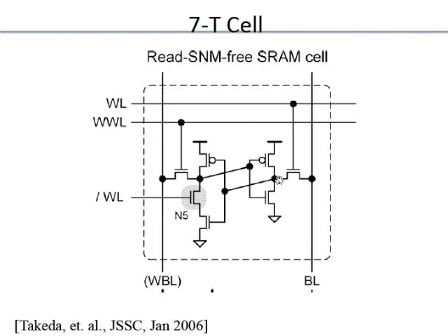Now if the data is 0 is when we said we could have a problem of flipping the cell, because when the data is 0 here, I have a current flowing through here which can cause this to go up and bump, but that is prevented by this. When this is 1, there is no issue because bit line is also pre-charged to 1, this is also 1, there is no current. You wait for some time, if the bit line is not discharged, you just call it a 1 and go ahead, right? So the way you sense a 1 is, you give it some fixed amount of time and then you sample the bit line. If it is not discharged below a certain value, you say it is a 1. If it discharges, then you say it's a 0.